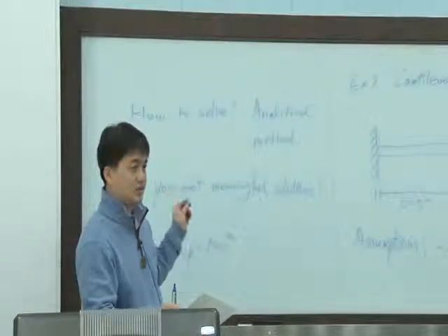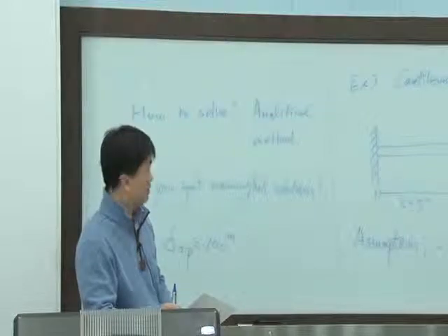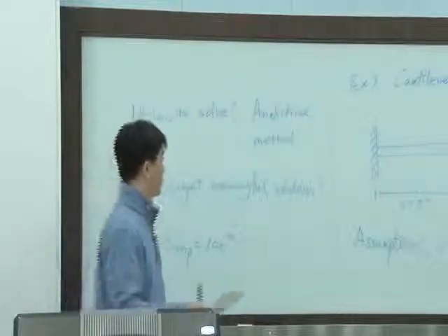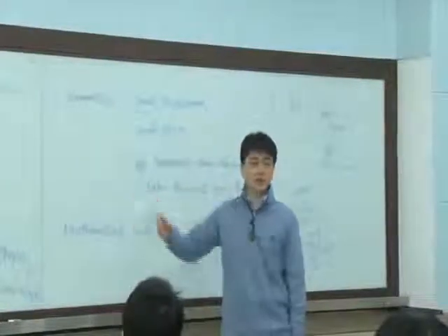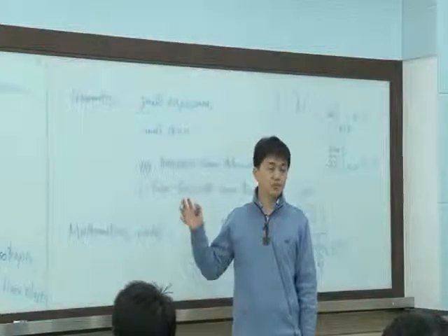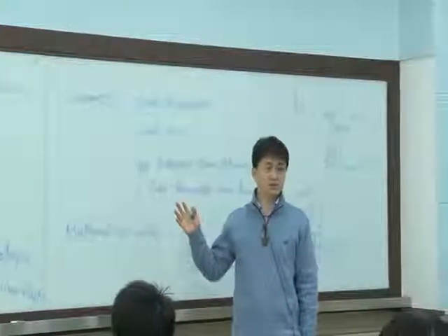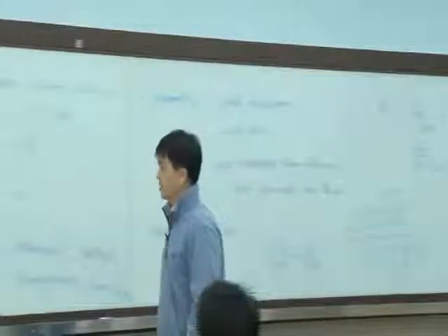This is clearly a very, very large displacement, right? But we use the assumption of small displacement. So if we get a large displacement, we can say that the solution is totally wrong. We cannot use it, right?